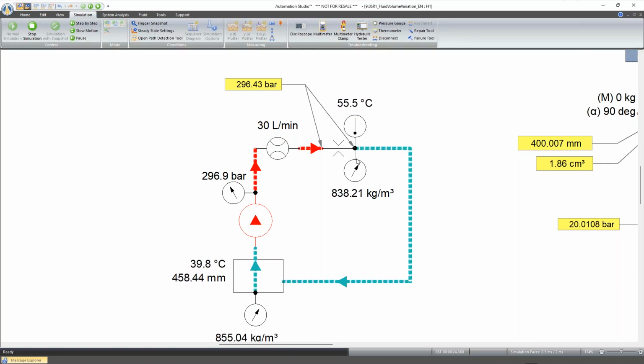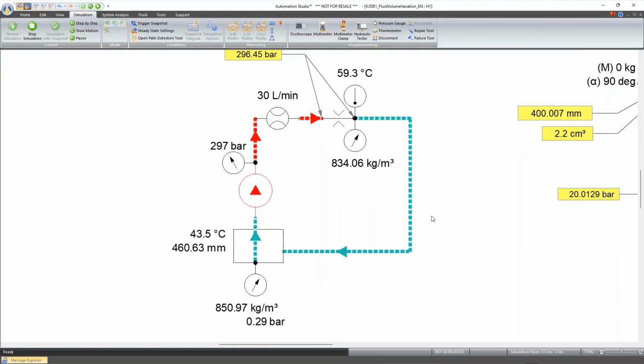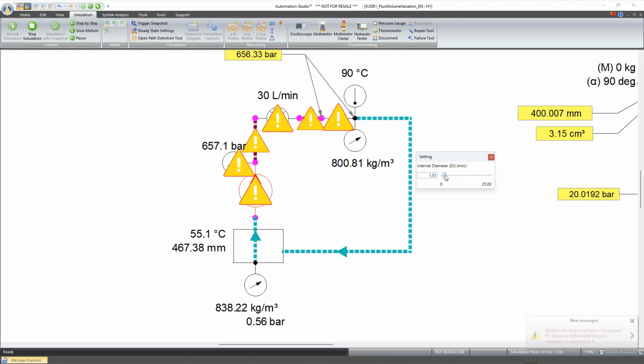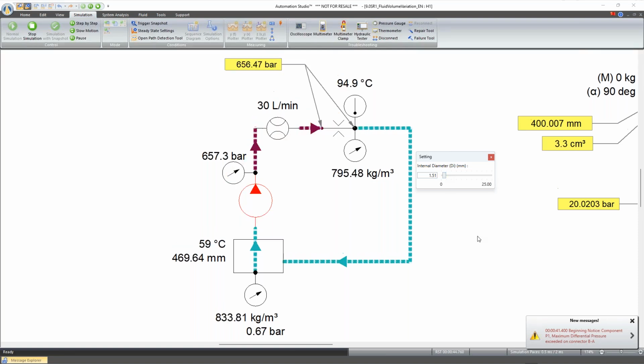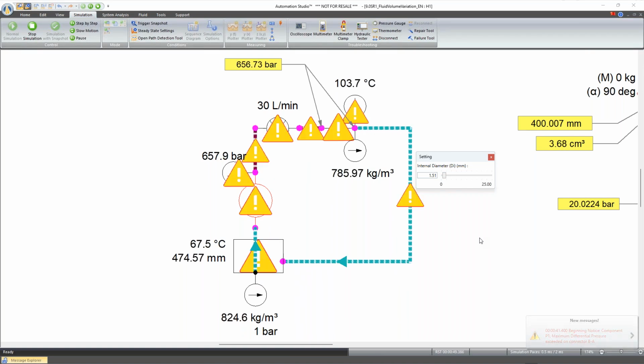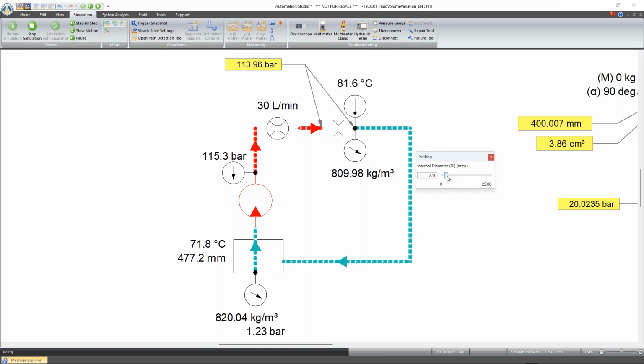And this, of course, causes the changes in the density of the oil, which then increases the phenomena of the thermal expansion occurring with the volume in the lines and the reservoir. We can see the height in the tank rising. If I set this even narrower, yep, my temperature increases way faster now. I'm also getting those warnings as I still have the option turned on. And I can see the effect on the fluid density here.